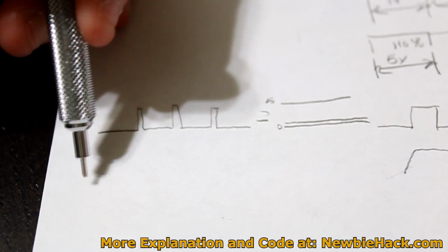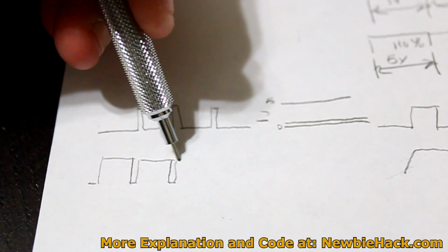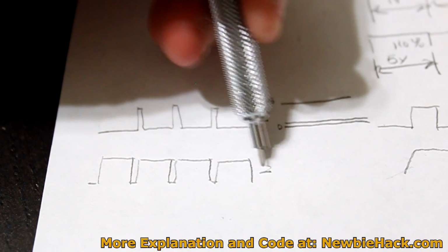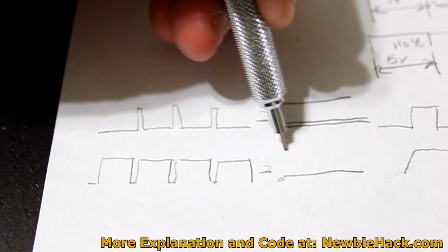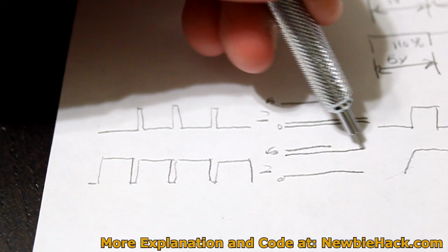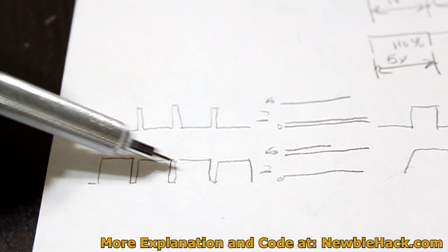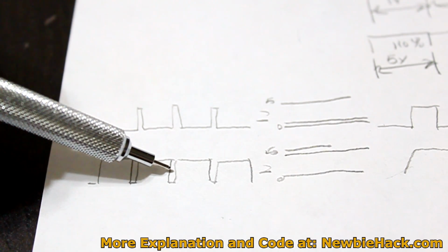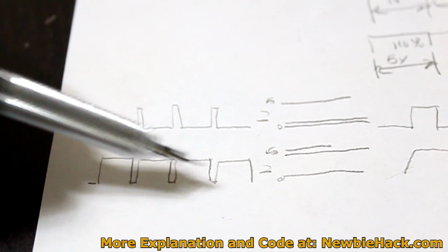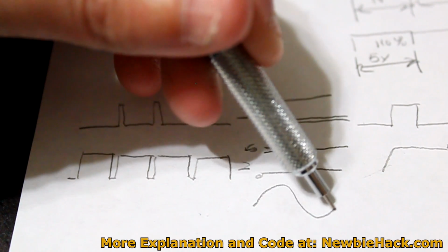If you had a large pulse width modulation, with a lot of pulse on the top, that would equal more of a 5 volt or close to 5 volt voltage. And with the microcontroller, if you modify this pulse width modulation using a loop or something else, you can actually create an analog voltage of whatever you want.